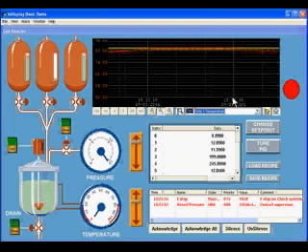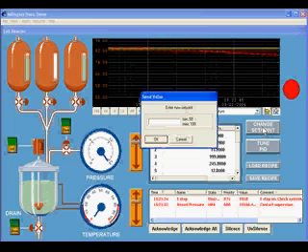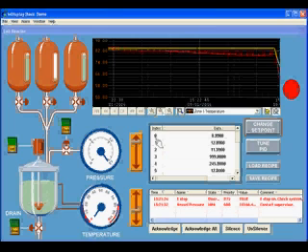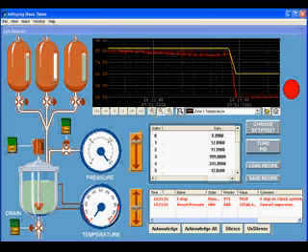In our example, we have used objects on the ioDisplay screen to communicate with our trend window. For example, to change the set point, represented by the yellow line in our trend window, we can click on the Change Set Point button. Let's enter a new set point of 70 degrees. We have also used the animation of a slider to change our set point.